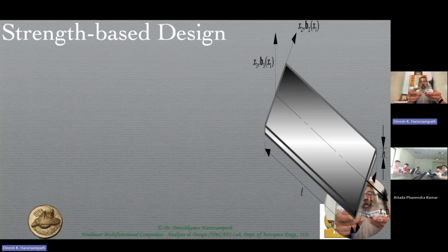Now if you look at the wing over here, the wing tip is facing a slightly higher angle of attack compared to the root. This is kind of common. There are other designs where it's exactly the opposite, what we call the wash out or the wash in. This is even more common in the case of helicopters, where you would have pre-twist in the rotor blade. In either case, the cross section, wherever you take it, will make different angles with respect to a fixed frame, let's say an aircraft fixed frame or fuselage fixed frame of reference.